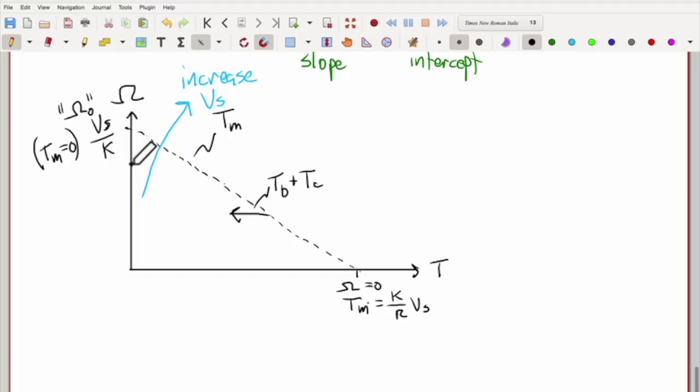And so what you really get is this other line that looks a little different, and it's lower actual torque than the ideal magnetic torque. And it's usually not quite parallel because you have this velocity dependent torque and this fixed torque, so it's a slightly different angle like that. Okay, so this is the real actual torque you get.